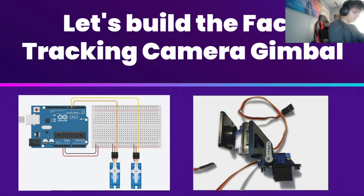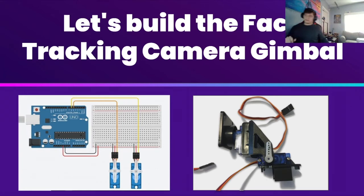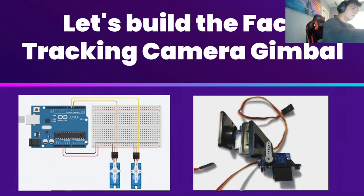So let's start by assembling the gimbal, and then from there we'll connect the servos to it. Initially, within the servo packets come these white parts that connect to the servo. We're going to have to cut that a little bit so that it can fit inside the gimbal. I'll do this along with you guys to guide you through it if you don't know how. If you have scissors or a sharper tool, you could use that, but just be careful. We don't want anyone to get hurt.